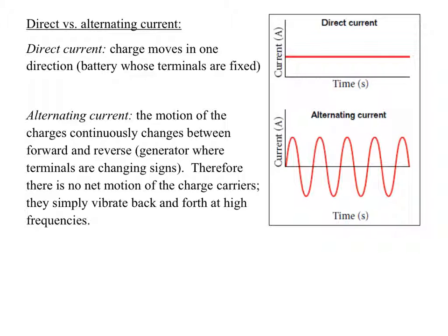The stream turns the device, the device spins an axle, the end of the axle spins a magnet, and the magnet is next to some coiled wire. The magnet spinning induces a current. Induces means causes a current. The current in the wire starts to generate. If the poles of the magnet keep switching, the current goes one way, and then the current goes the other way. It changes the direction of the current.